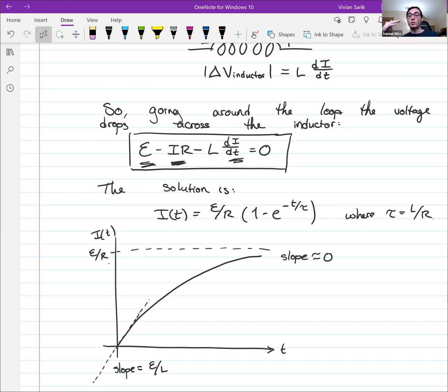Once the inductor starts working, it will slow down the rate of change of the current. And if the rate of change of the current decreases, that means the slope of the current function is smaller. So the inductor becomes less and less effective as time goes on, because in doing the inducting thing, it is reducing the thing that makes it work to begin with. So inductors, if you wait long enough, just stop doing anything.